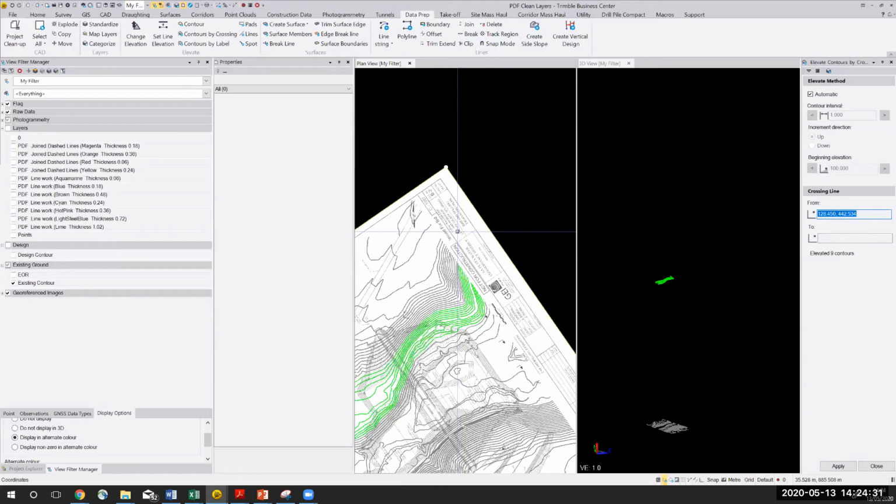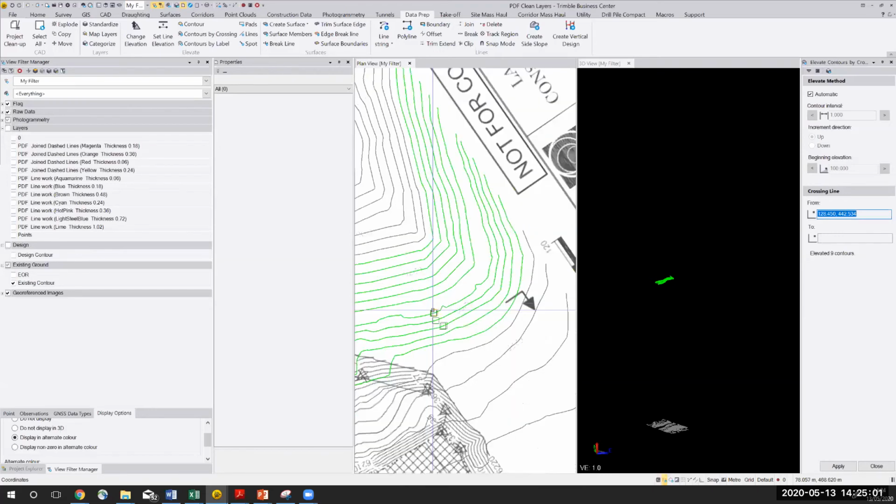If you had to, you could then send surfaces out to be set out or put into machine control. But I would imagine once you've won a tender, you would receive the digital files, the CAD, DXF or DWG files or whatever Genio files that you could then use for set out, or verify your PDF drawings just to make sure, because there could be some inaccuracies in the PDF for set out purposes.